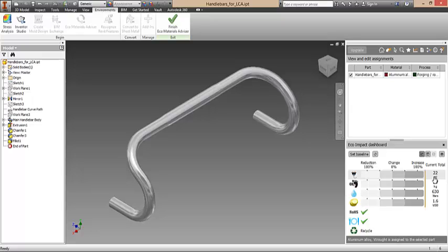The Ecomaterial Advisor has a database with the amount of energy, water, and CO2 released per unit mass for each of these materials. It also has data on the resources used in different manufacturing methods. The numbers we see here are the values applied to your unique model. Record these numbers on your worksheet as you will need them later.